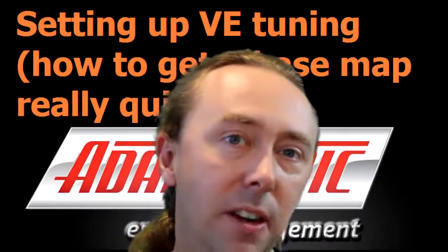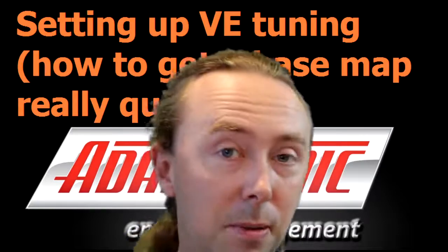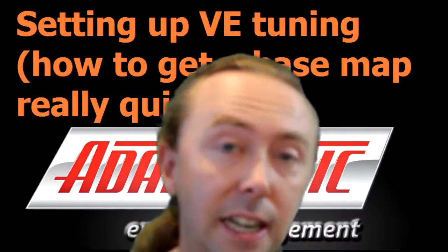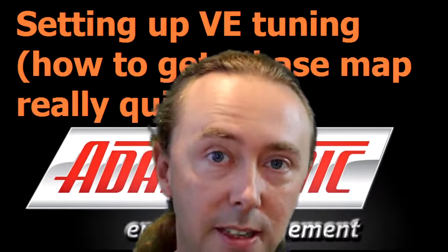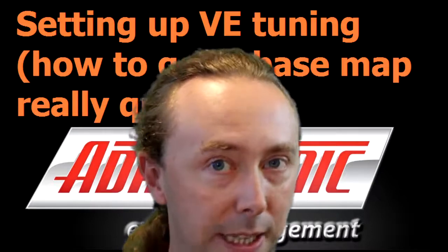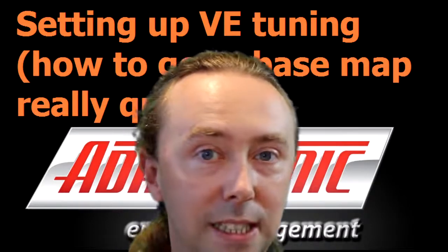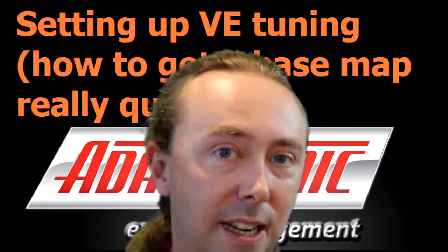As far as I know, Adaptronic were actually the first guys in the aftermarket world to introduce VE tuning. We implemented it back in December 2009 and since then most of the other aftermarket ECU manufacturers have introduced it as well. The main benefit is that it allows you to generate a base map really quickly, and even if you don't have all the details of your injectors, it's still a lot quicker than to guess millisecond values from